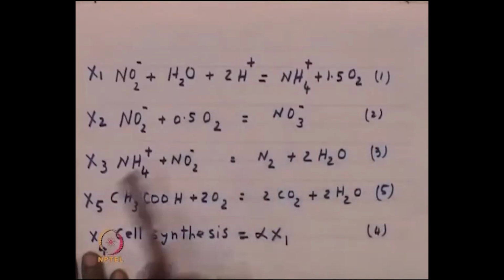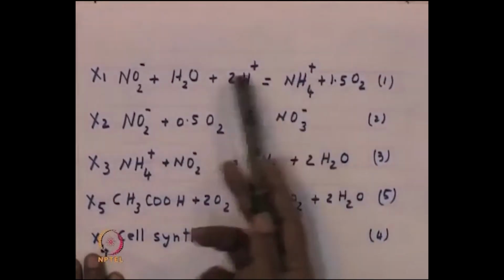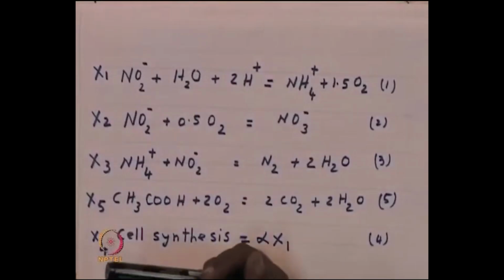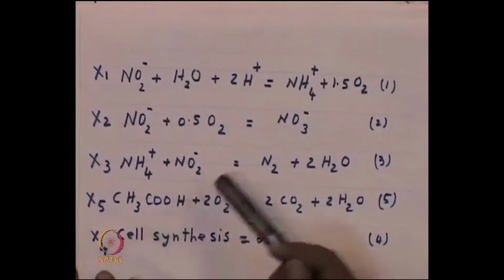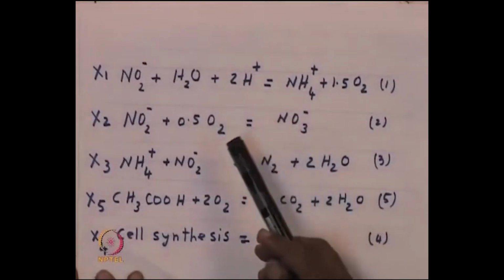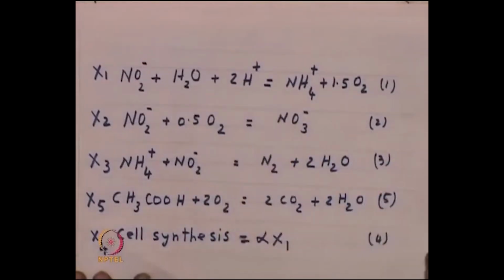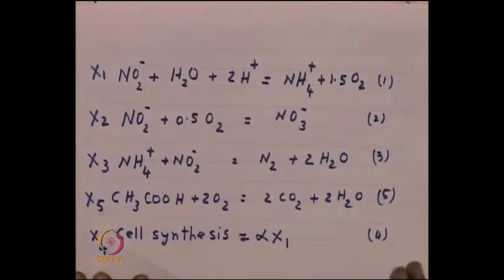What does x 1 negative mean? It goes the reverse way, and therefore, no cells are produced, and therefore, no sludge is formed. Therefore, you do not have to deal with the problem of sludge in waste treatment. You understand? See, the insights that it can give you are enormous.